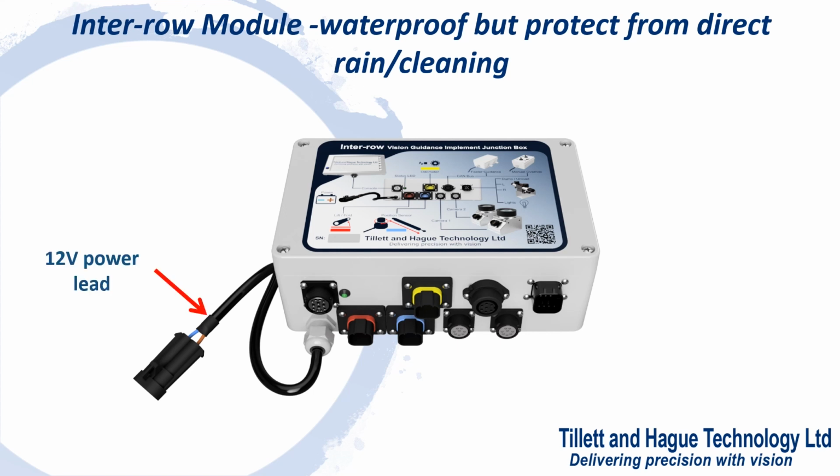System 12 volt power comes into the module on a flying short lead with a 2-pin connector. An LED power indicator provides system status information via blink code. On power up, it's continuously on for a few seconds before going into a slow 1.5 second blink, indicating it is running but idle. Once the working screen is displayed, the blinks speed up to a very rapid but even blink. Other blink patterns are associated with error codes that are listed in the reference manual.